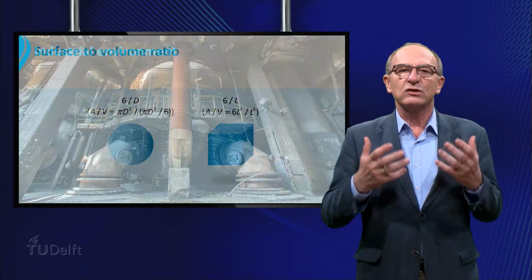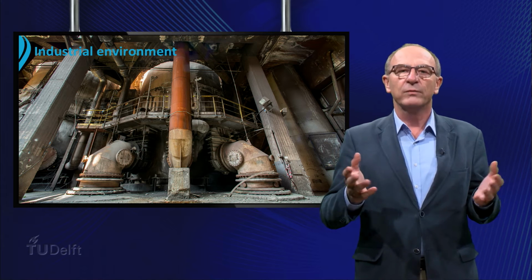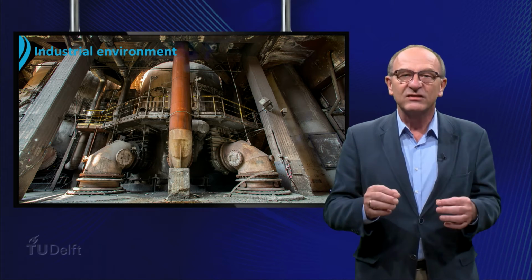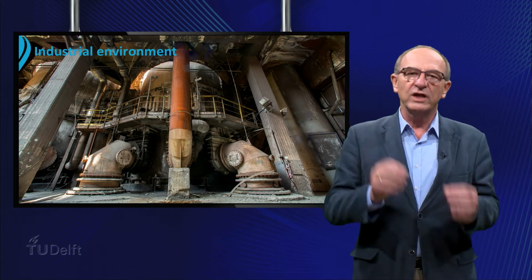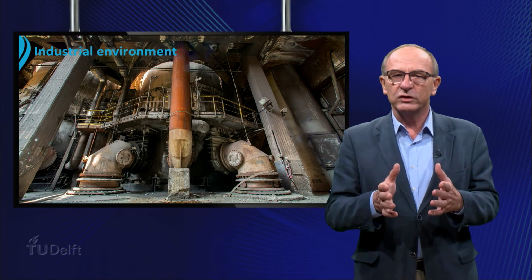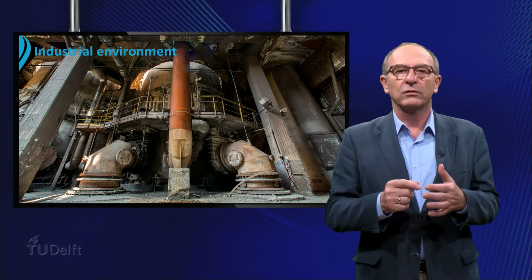In industry it is quite similar. A lot of chemicals are produced in reactors where heat is produced. If heat is released during the process, it's necessary to cool down the reactor for safety reasons. Often the surface area is not sufficient to cool the process, and heat exchanger tubes are used in the reactor.